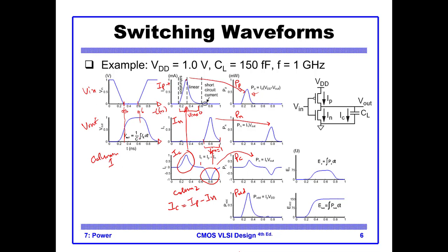They are all multiplied with Vout, and you see the supply current is the product of IP. IP is used because the power is drawn from the supply voltage only when the PMOS is on. When the NMOS is on, no power is supplied by the VDD. So all the power supplied is in the charging cycle.